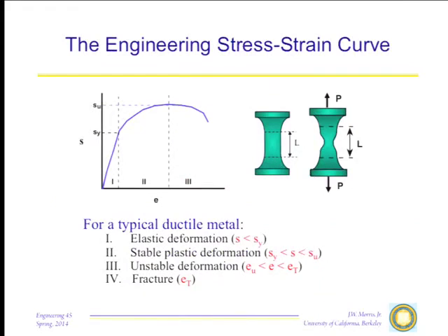What's called the strength ratio, the ratio of the ultimate strength to the yield strength, is a design parameter that is often specified in specifying structural materials. And the reason that's done is that this is your cushion. If you do happen to have loads that exceed the yield strength, you don't want the material to deform at all, but if it does deform, you don't want it to break. And this is your cushion, the margin above the yield strength that you have to work with in which the material will not come apart.